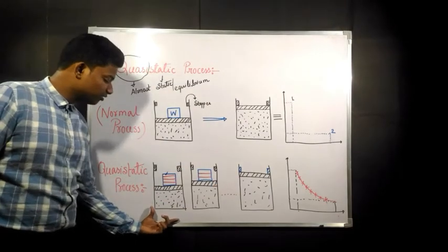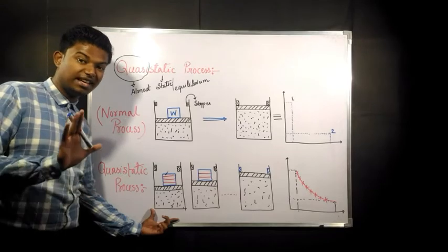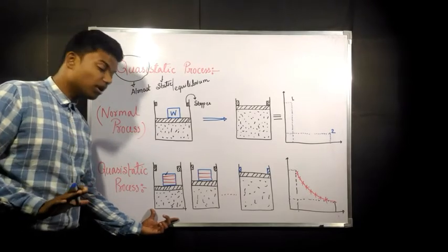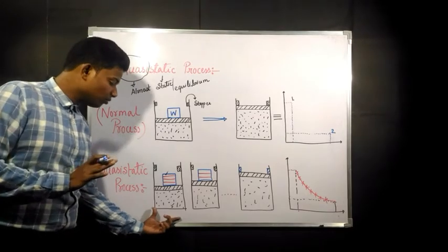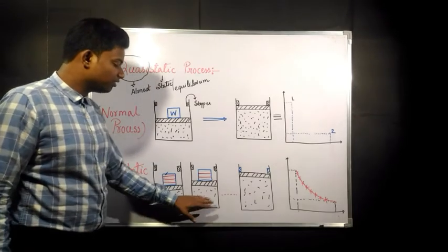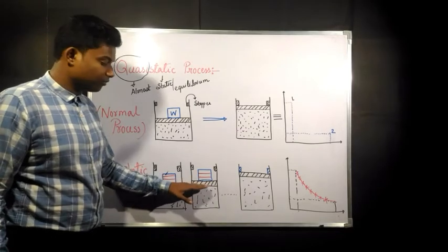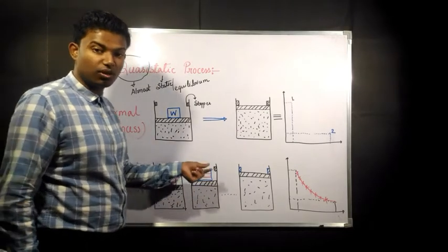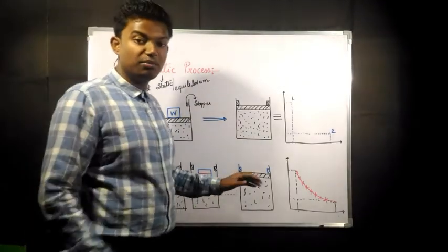Now this process, I will say that it is in an equilibrium state. That means in a state. In the last video we have discussed the state. So what does a state mean? That means it is not going to change now. Now what happens? If we remove one of the pieces, to make it equilibrium, this unbalanced pressure will try to push this piston a little bit. Okay, like this. If you take out one of the pieces once at a time, then it will pass through a number of equilibrium states.